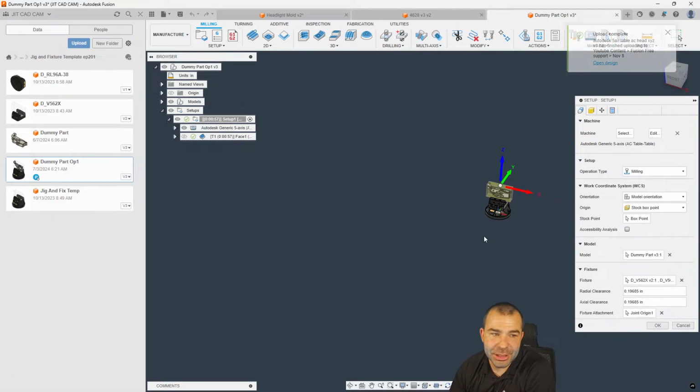Depending on how old your machine is, your processor might not be able to keep up with the lines of code. Yeah, very common. I get asked about things like data starving the machine. When anybody says, hey, we're looking at getting a new machine, what do you recommend? One, always get fourth axis pre-wire, 100%. Unless you're buying a 5-axis, then it's already there, right? But the second thing is by all means, guys, a probe and high-speed machining. I've seen hours come off cycle times because of things like high-speed machining and look ahead.